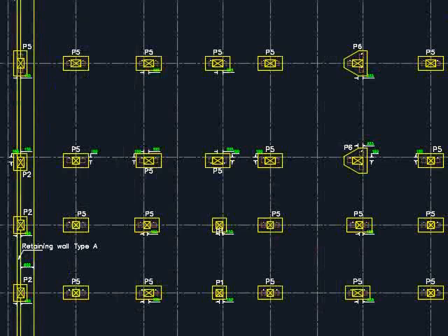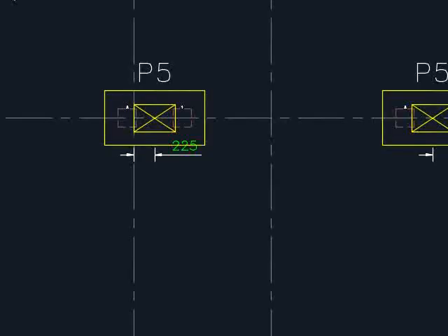This is a typical foundation key plan. What we see here is a series of foundations. There will be the proposed foundation size, the number of piles, and the columns indicated. The key plan here does not provide the numbers of the columns.